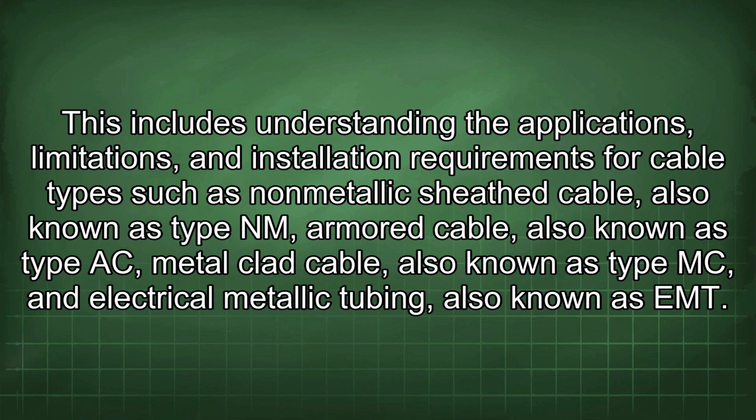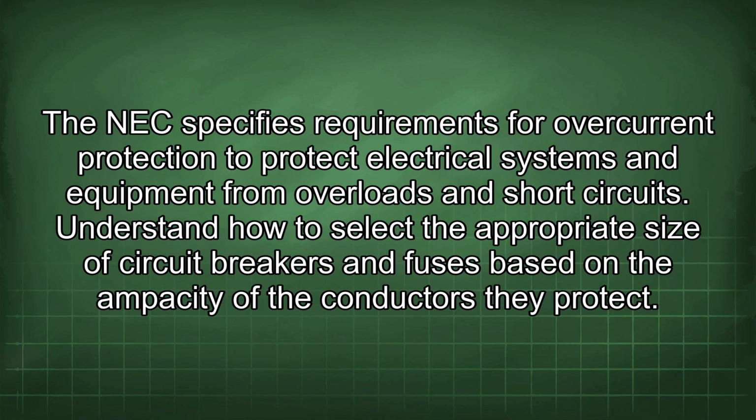This includes understanding the applications, limitations, and installation requirements for cable types such as non-metallic sheath cable, also known as Type NM, armored cable, also known as Type AC, metal-clad cable, also known as Type MC, and electrical metallic tubing, also known as EMT. The NEC specifies requirements for overcurrent protection to protect electrical systems and equipment from overloads and